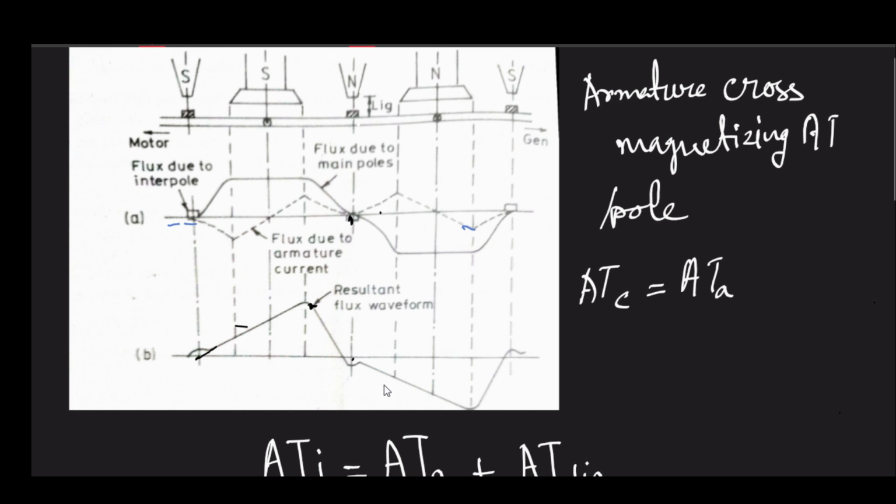The essence is that below base speed, although your flux remains constant, for a heavy load your armature current, either for electrical or mechanical load, will be excessively high. That will produce a considerable amount of armature MMF, and therefore it will cause a tangible deviation from your nominal field flux distribution.